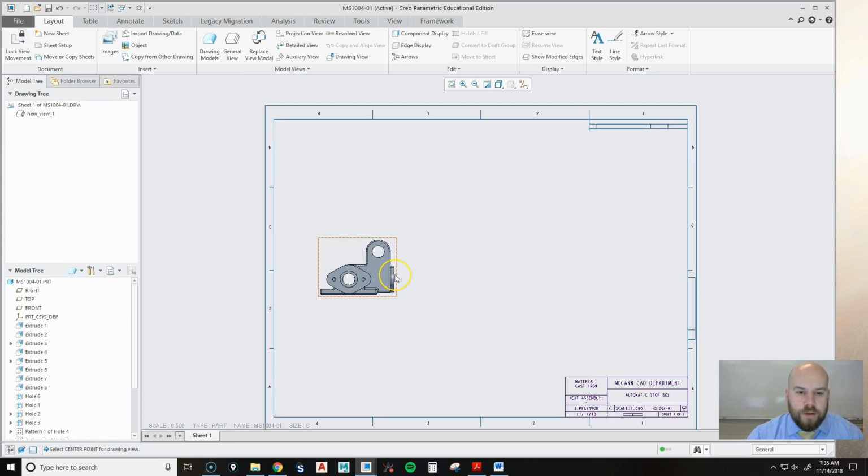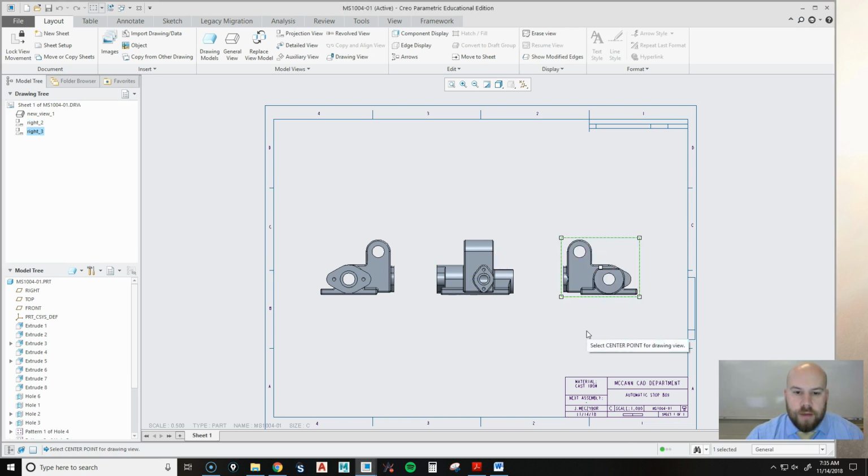And I know I need to see this side over here. And then I'm going to need to see the back. So that's probably going to go over here too. So let's project that. So I'll click it, pick Project, Side View, click that one, Project, Back View.